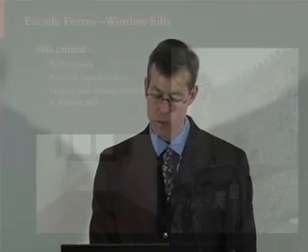So you see a flat at the lower right towards this concave hip at the lower left. So they still had something that was a different shape. It was still distinguished from the other floors, but it shed water better. And then if you look at the ones that were flat, they've usually learned over time and been modified in some way. So this one at the lower right, there's a photo at the upper right of the same window. The stone was deteriorating, and they put a metal cap on it as a retrofit to try to keep water off it and shed water better.